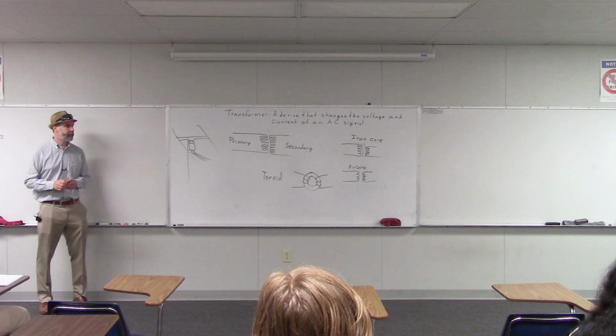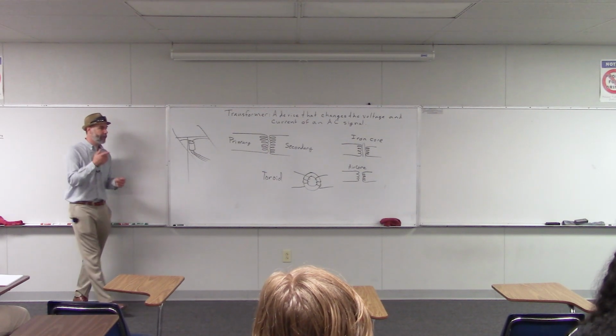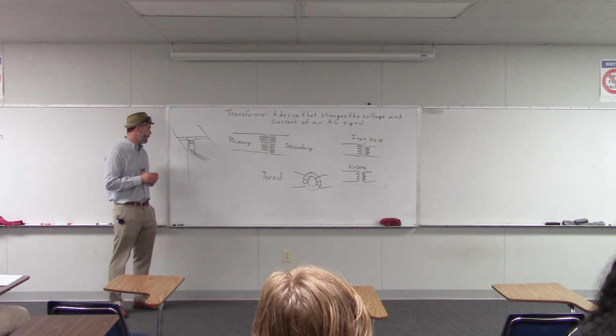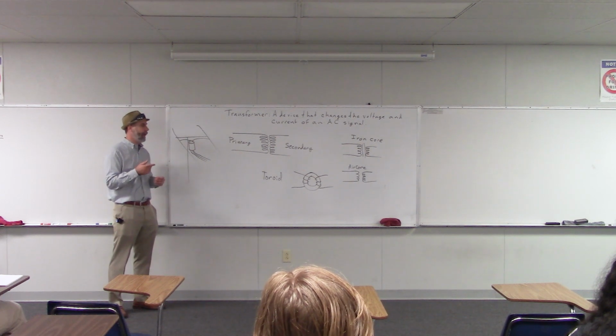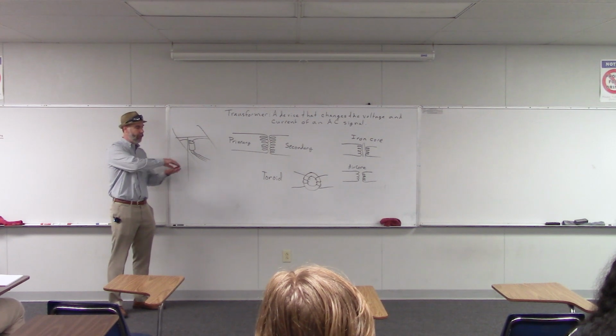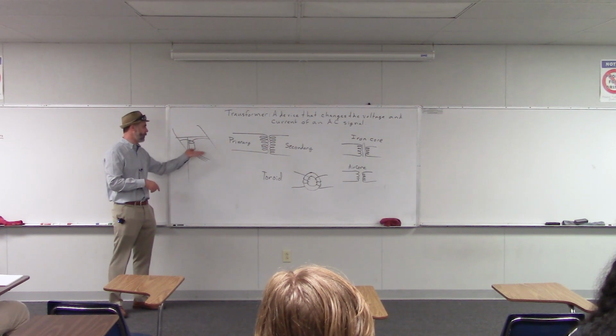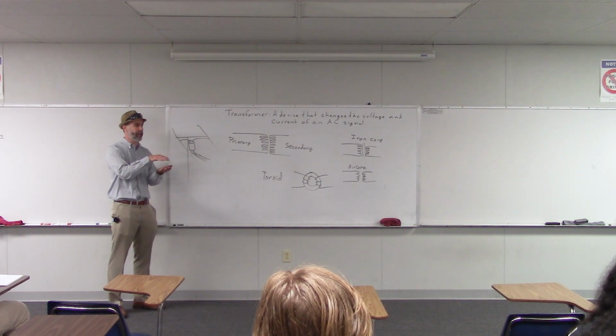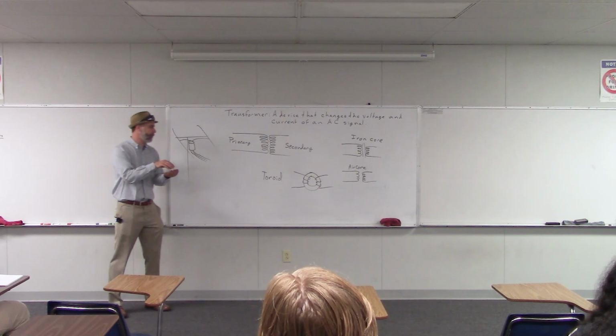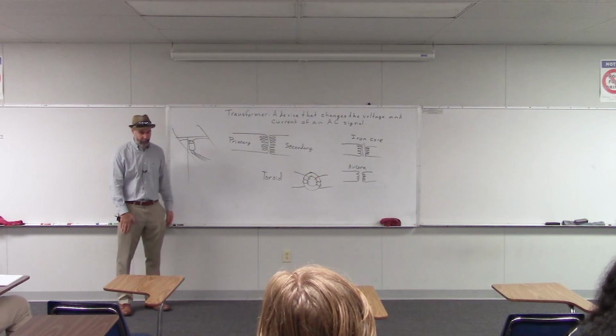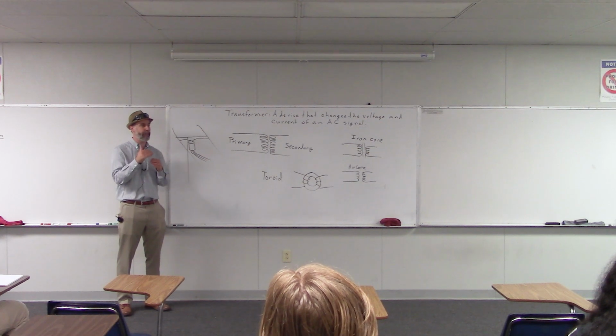So is a power brick just a transformer that you plug into a wall to charge your phone? So that's half of it, and then the other half is the rectifier. The transformer takes the high voltage AC and turns it into a lower voltage AC, and then our electronic devices typically run on DC power.